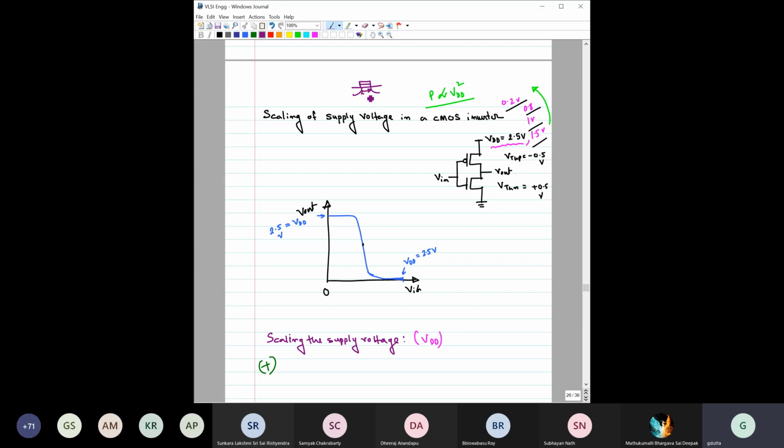And this is the gate length, right? So suppose this is the source and you have grounded it, and here you have applied VDD. So this is the gate length, right? And VDD is okay. Suppose VDD of 2.5 volt is okay for this particular gate length. But if we now shrink it for better performance, obviously the gate length has reduced. At the same time, there is no other way, you have to reduce this VDD as well, because otherwise this material can even break down. So all these things also come with the technology scaling part.